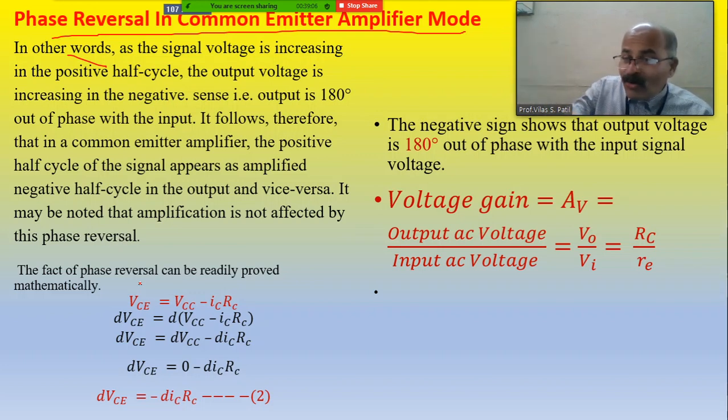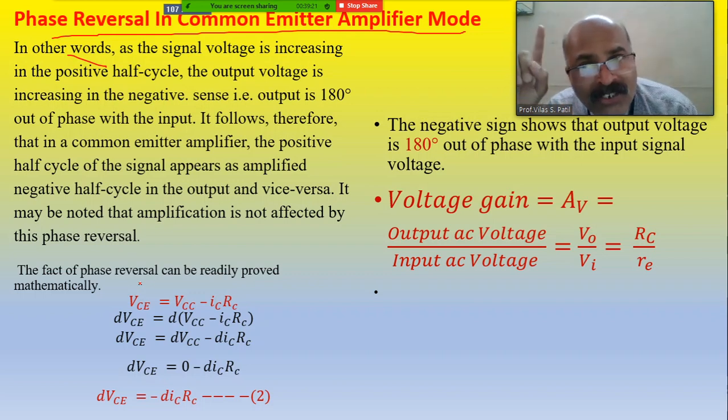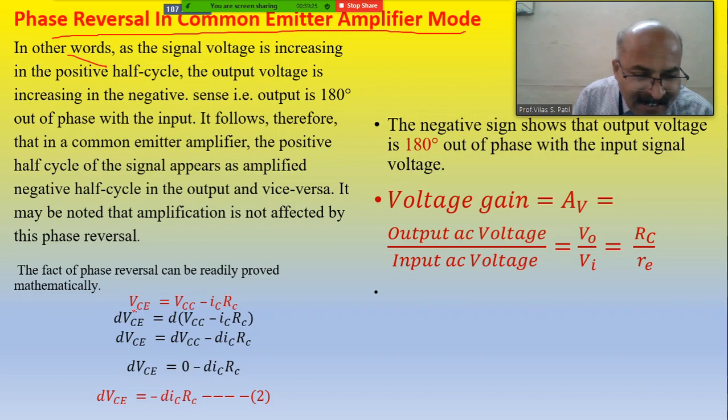It is correct. Okay. In this, VCC is the constant. IC will be changing, we know that, and due to that VC is also changing. But what is the constant? The constant is VCC. Okay. Then consider this relation: VC is equal to VCC minus ICRC. Then differentiating on both sides, take the differentiation of this equation.